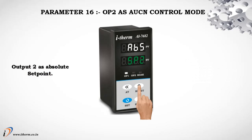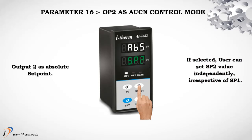Parameter 16, Output 2 as auxiliary control mode. Output 2 as absolute set point. If selected, user can set the Setpoint 2 value independently, irrespective of Setpoint 1.